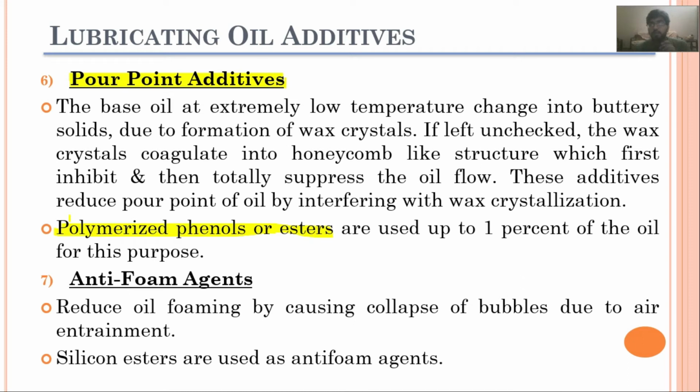These pour point additives do not allow the coagulation of these wax crystals. They reduce the pour point by interfering with the wax crystallization.